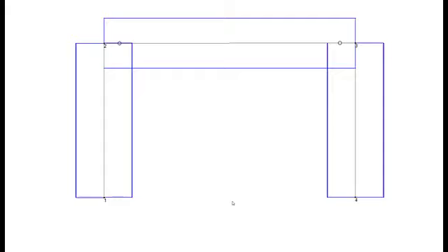So what you see on the screen is the center-to-center modeling of the frame, where I have displayed the sections outline. Some of you might think that it is not right to have the top flange of the beam go beyond the top of the column. But if you think closely from the perspective of mathematical modeling, this does not distort the actual results. As a basic assumption of structural analysis, the load is always thought to be acting at the center of the beam. So as long as the beam center line is flushed with the top of the column, this creates no problem whatsoever.